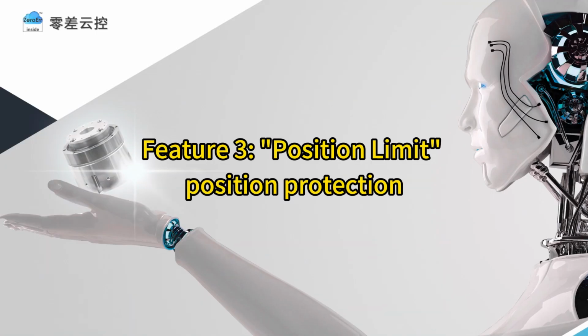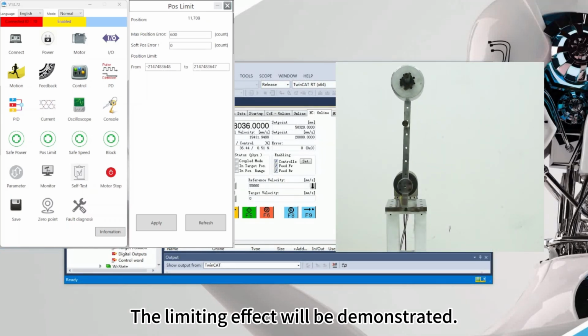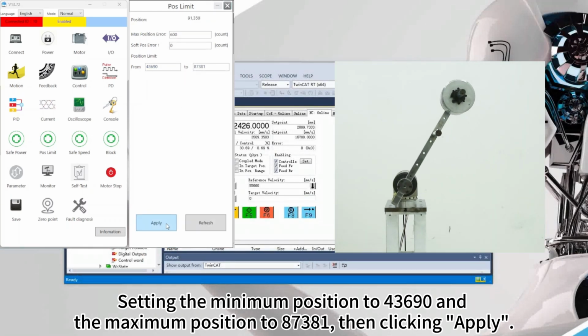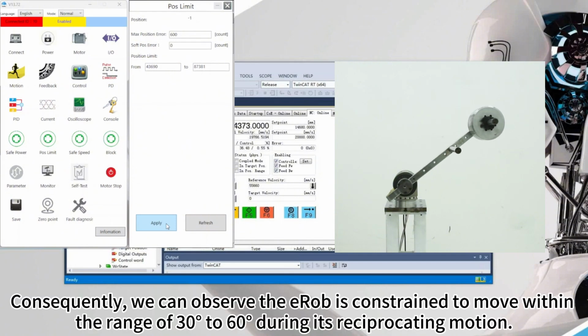Feature 3: Position Limit, Position Protection. The position limit parameters are used to set the minimum and maximum position limits for eRob movement. The limiting effect will be demonstrated. Setting the minimum position to 43,690 and the maximum position to 87,381, then clicking Apply. This establishes a range where the eRob's minimum position corresponds to 30 degrees and its maximum position to 60 degrees. Consequently, we can observe the eRob is constrained to move within the range of 30 degrees to 60 degrees during its reciprocating motion.